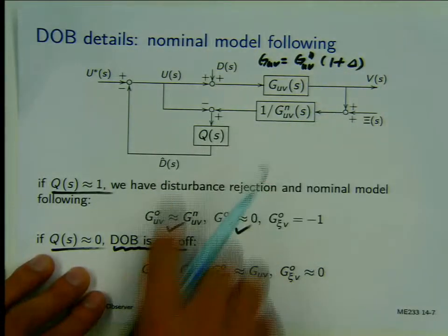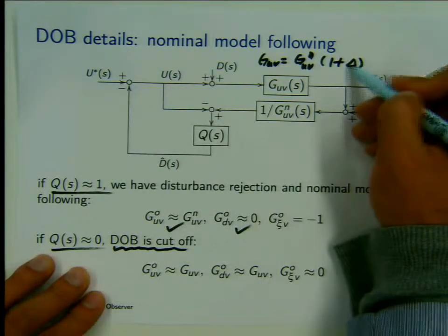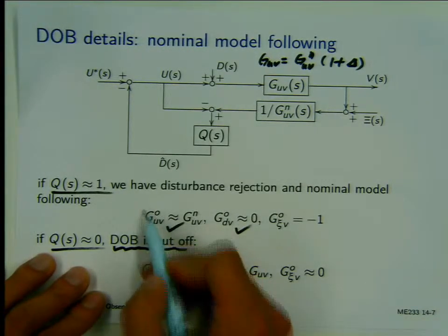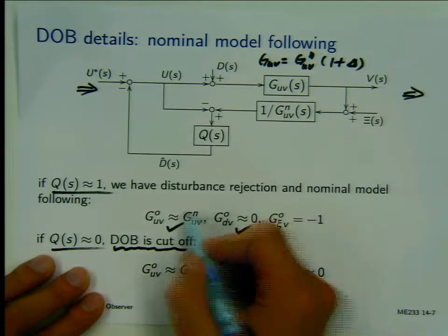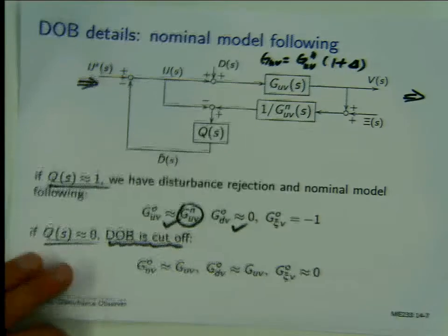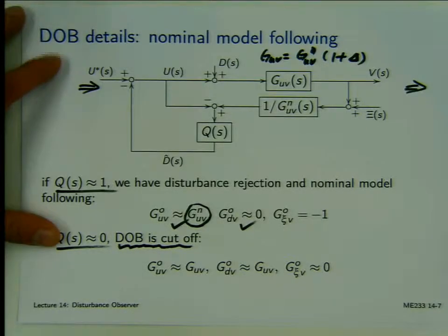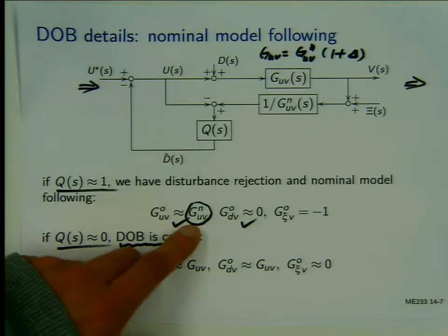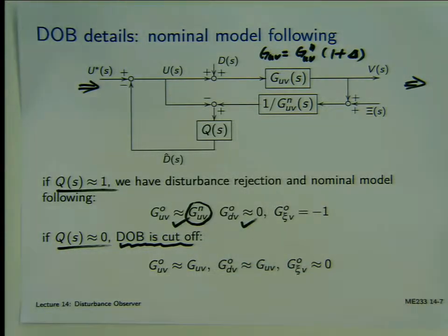However, by doing this disturbance observer design, you can make these internal uncertainties somehow disappear, and all you see from this side of the system to the outside is just this nominal model of the system. So that makes the design of feedback or feed-forward controllers much more simplified, because you know the nominal model, and you can design your controllers based on this nominal model now.